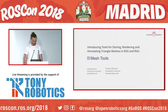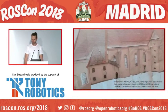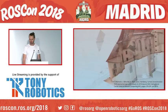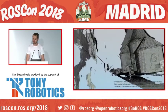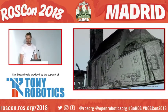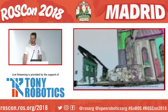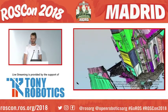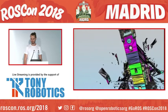Thomas and I focus a lot on mesh representations and their research in robotics. Coming from a high resolution point cloud, or many point clouds registered to each other, we can reconstruct these using, for example, the Las Vegas Reconstruction toolkit, namely LVR, with the marching cubes approach, and reconstruct it to a mesh as we see in the video, then retessellate the triangles to reduce the data, and later also apply textures to keep the color information, as we will see now.